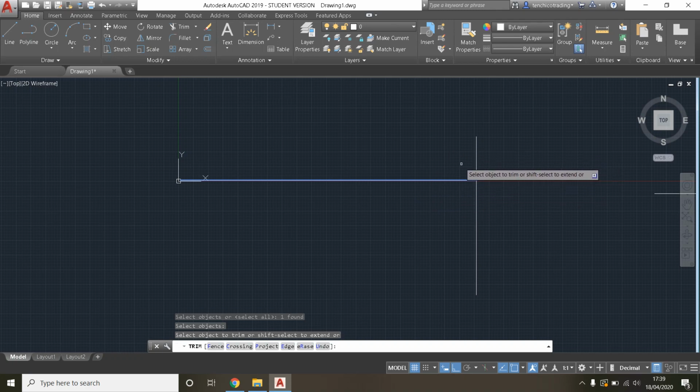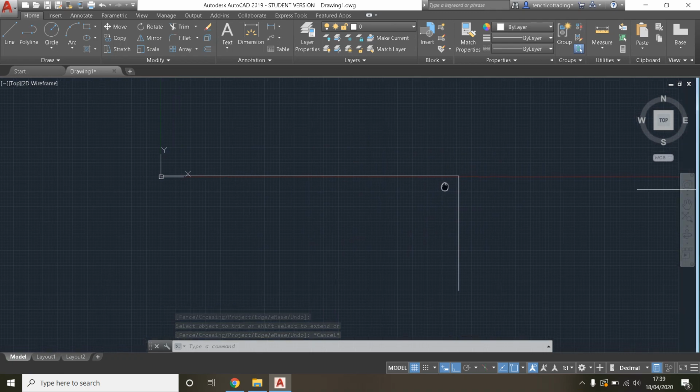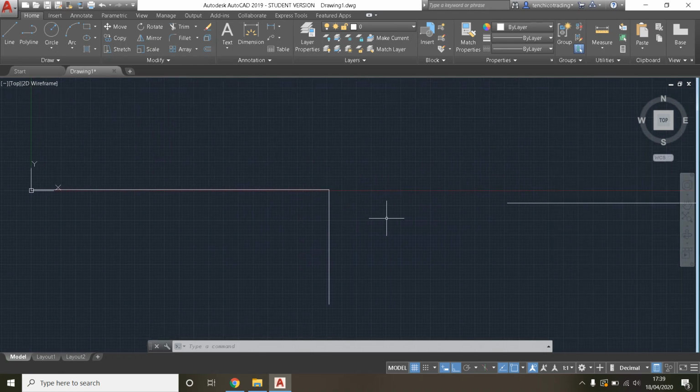Sharp. Now the next one we're going to select is the line we want to trim out of our drawing. If you can see, if you just move on top of that small line there, it's going to show a red X. That means yes, you can trim this away. Or you can move to this other side, it can trim this away. We just want to get rid of this one. Just click your left click when you're on top there, then shanana, it is gone. All right, escape. You'll find that this is how your trim tool works. It comes in handy, makes everything neat.